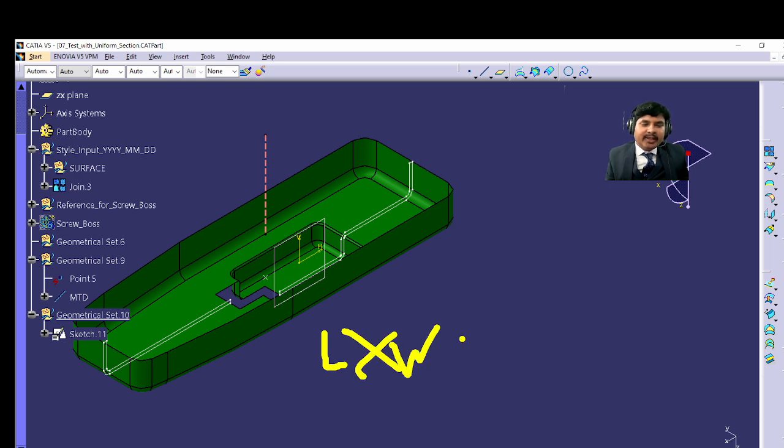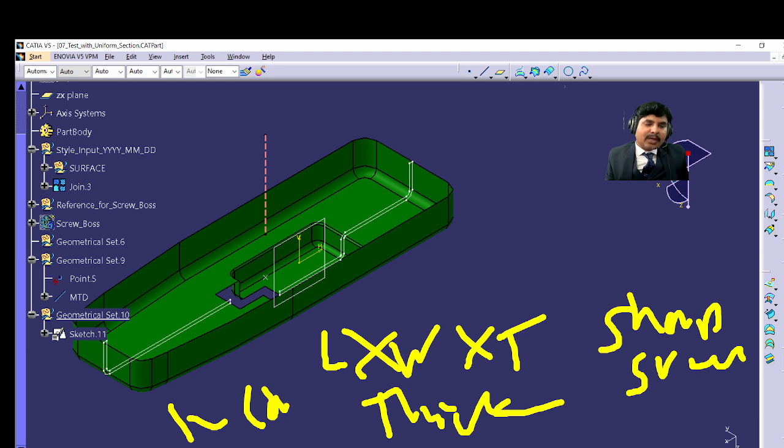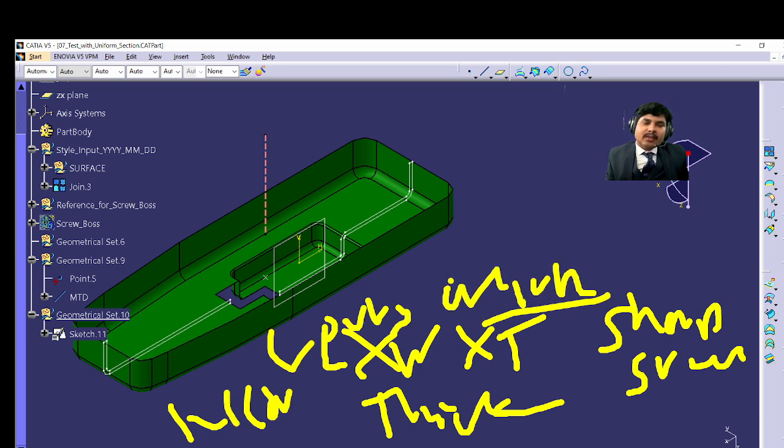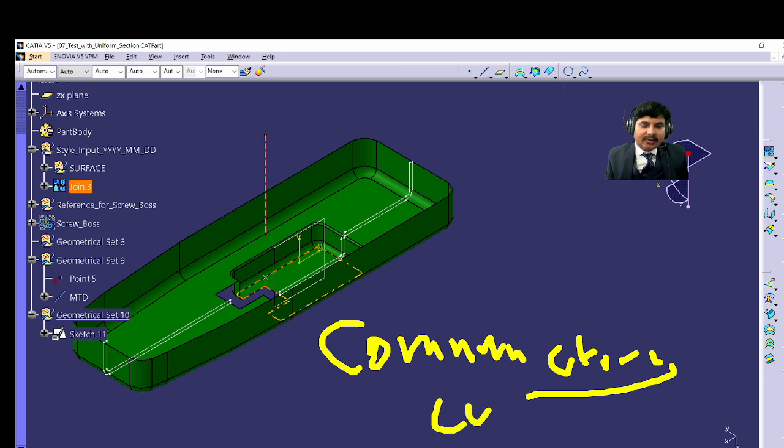Length, width, thickness, meaning shape of part, size of part, then thickness of part, then number of features on part, the locations of features, which features, cutout information, gap, flush, clearance information. The section is the communication language. We can call the section a communication language or method of engineers, the trims design engineer. So by sections you are representing what you want to say.